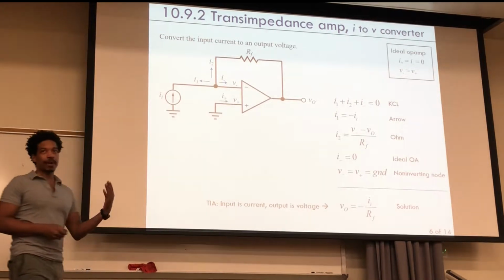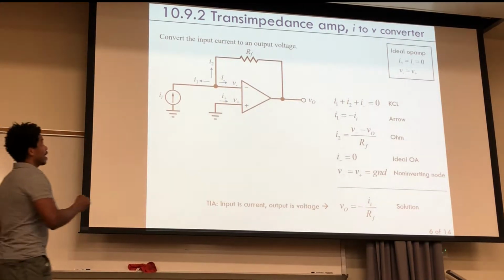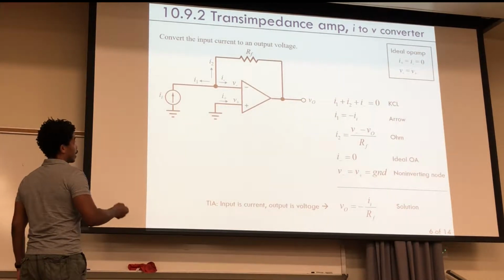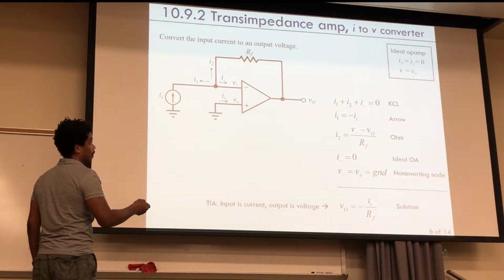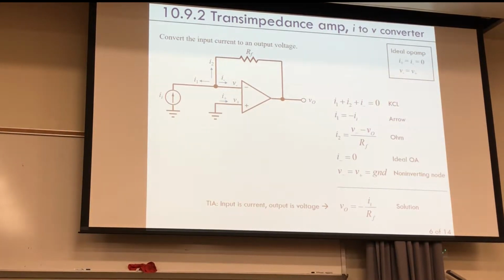Okay, so it's not final minus initial, like what delta usually is. It's the opposite of that. Okay, if this arrow was going the opposite direction, going into that node, then I would have V0 here be negative there. Okay, so you got to be really careful about your directionality of your voltages.